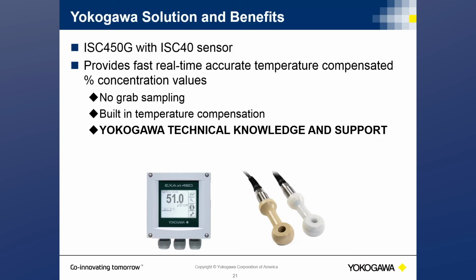So remember, with the other devices, they are specific for one particular chemical. Because all chemicals, all salts, everybody has their own concentration versus conductivity reading, it doesn't matter. One device does all the conductivity readings, and we just have to tell it in the analyzer what table to look at.